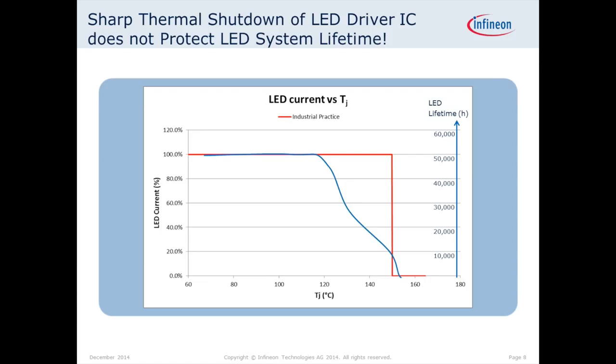So you cannot say that this thermal protection protects the LED lifetime or the lifetime of the electrolytic capacitors. It is just a protection for the very worst case to protect the IC. But if temperatures like 130, 140 degrees junction are reached, the LED lifetime has already gone down significantly.